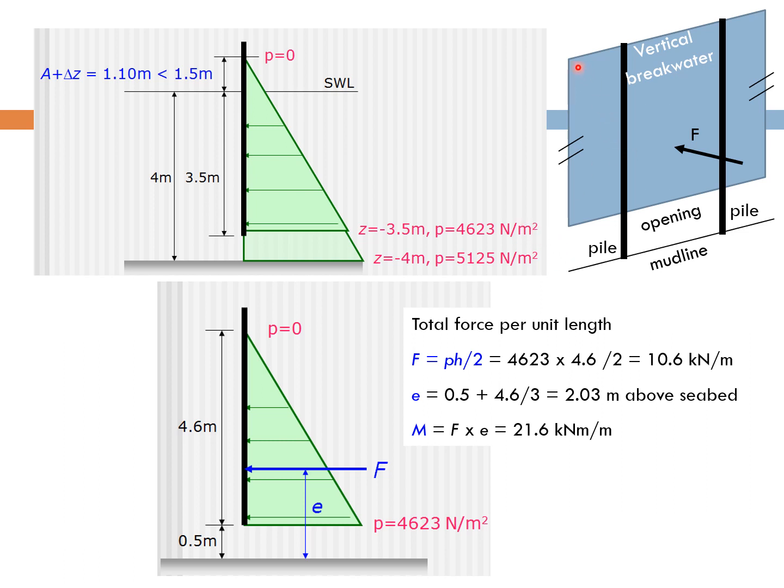Recall that the panel is supported by piles at regular intervals with openings below, and it is continuous in this direction and in this direction, into the plane in this figure. It is important that we derive the pressure on the panel. Although there will also be pressure on the vertical pile here, it will be minimal compared to the large surface area of the panel itself, which is why we omit the pressure that acts on the opening part here.